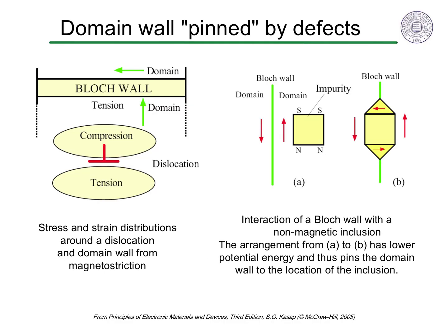The movement of domain walls is also inhibited by defects, similar to how grain boundary motion is inhibited by defects. Any strain at a domain wall due to magnetostriction will couple to the strain of a dislocation and then become pinned there. Similarly, impurity phases can pin domain walls by reducing their magnetic or magnetostriction energy.